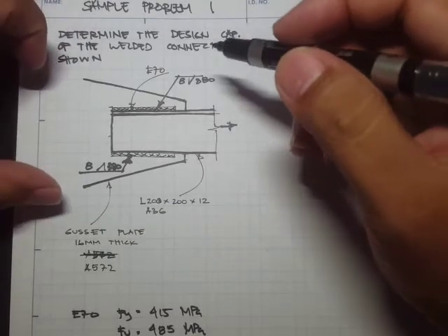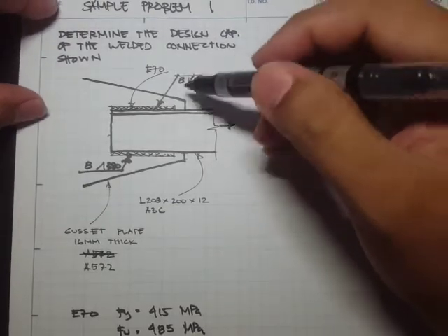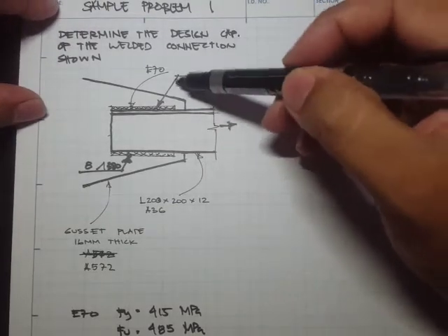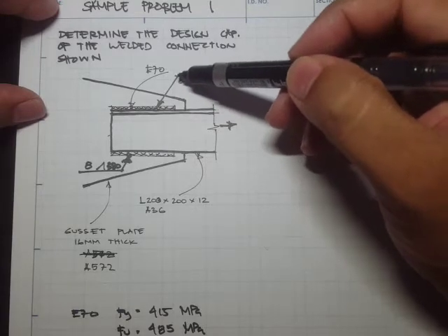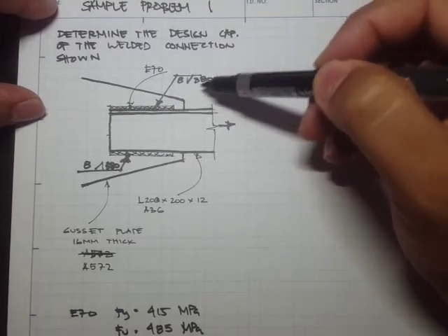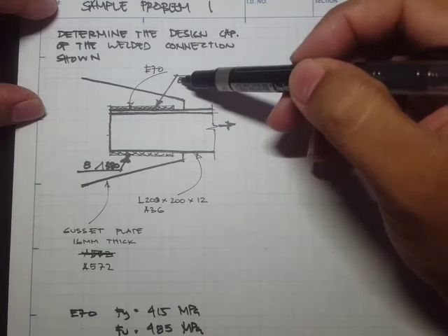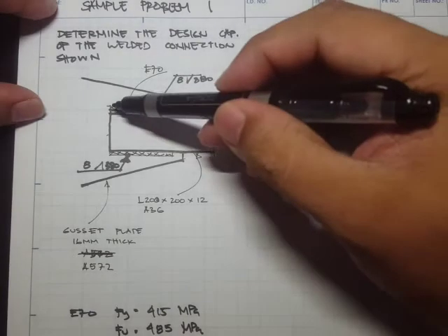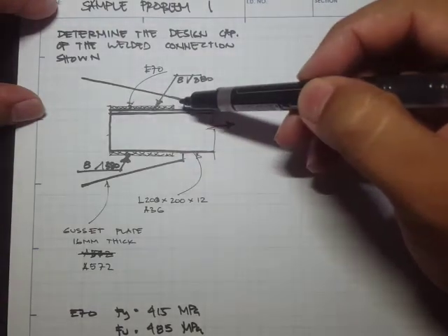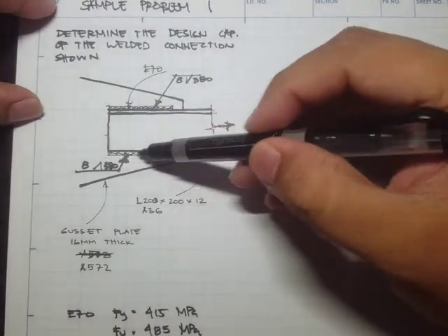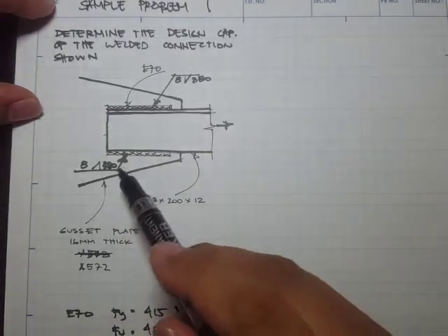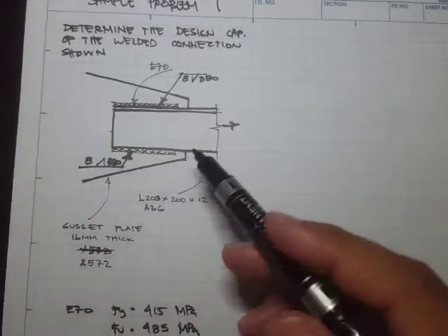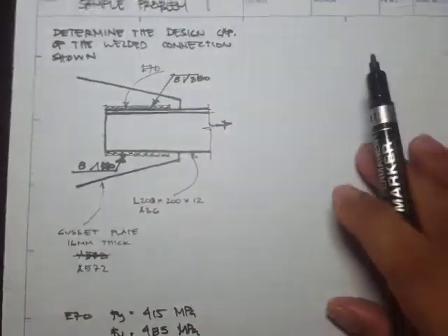Our welded joint is 8. This is the fillet size, and this one's the length. So it says here we have an 8 mm fillet size, and the length is 380. So meaning 380 here, and this is also 380. There's another bolt symbol here that I've provided.